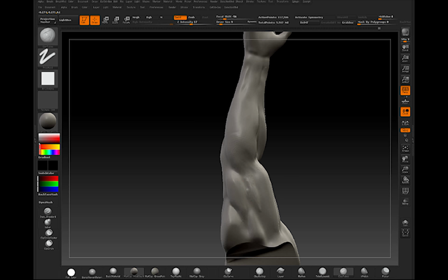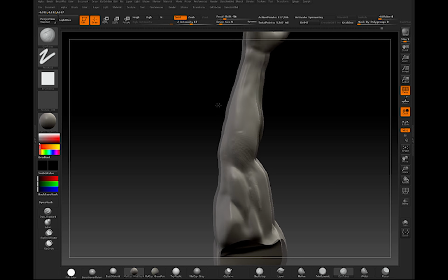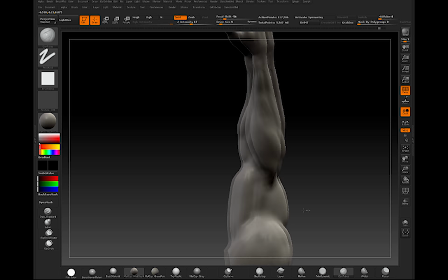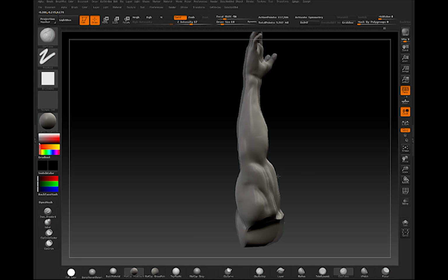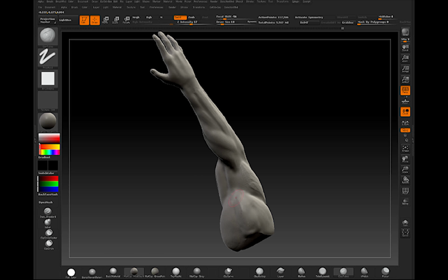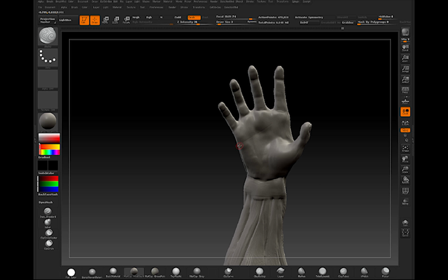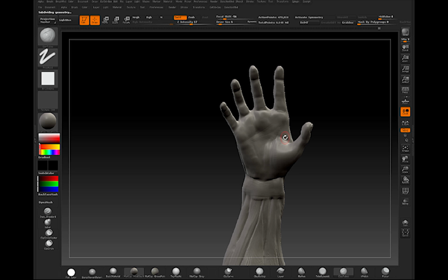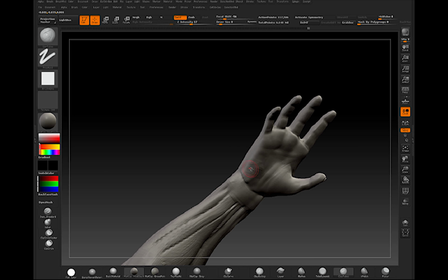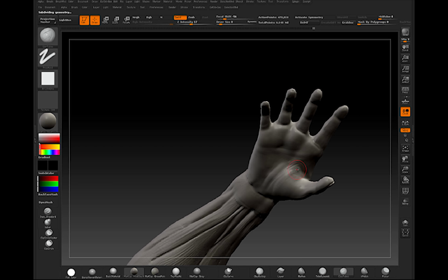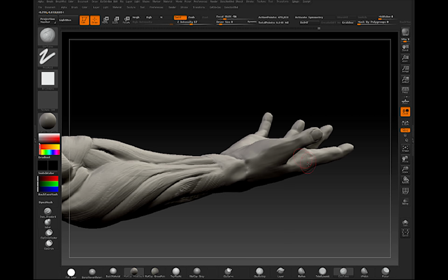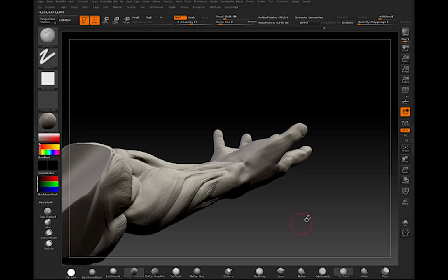The basics of sculpting and adding detail is you want to start on your lowest subdivision and build up. You don't want to move on to the next level until the last one was finished. So a lot of mistakes I see is people jump right up to the highest sublevel and start sculpting. That will just make your models look rough and bumpy, and it's bad practice. Another thing you want to keep in mind is working over the whole object, just like in drawing, rather than working on little sections.